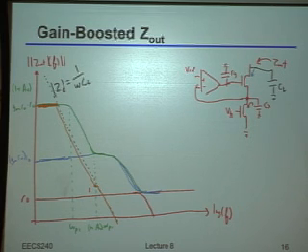But notice, actually, you can't really have this flat for too long, because there's no way you could ever have higher impedance than the capacitor itself. Okay? So if you zoomed in really, really carefully on this point here, what you'd see is that you'd have a 0, basically at the same point that you had a 0 here, but you'd also very shortly thereafterwards have a pole. Okay? Where that pole would be kicking in just to make sure that you keep following the capacitor curve. Okay? So far, is everybody with me?